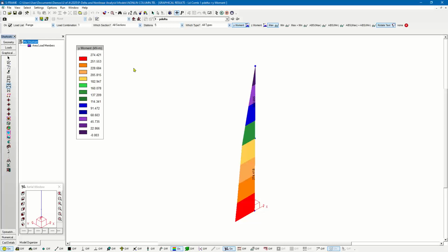Now, again, what's happening is that because we have 10 load increments, we have an ability to look at the results from each load increment and update the geometry matrix and the stiffness matrix after each one of those load increments. So we're doing a better job of capturing the results up until the point of that last load increment, whereas the P-Delta analysis is just looking at kind of the start and then at the end.